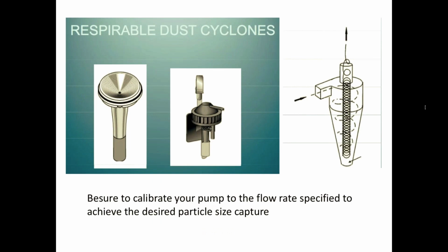Before we move on, another question. So you're saying that first I calibrate it, put it aside, put the new one in, and then take it out, put another one in, and calibrate. Correct. So let's say the first average was 1, and the second time I calibrate it again, I come up with, let's say, 1.5. Well, it's going to be lower, it's not going to be higher. So you come up with 1.75. So what do I do? You take the average of those two. That's the average flow rate during the entire period that it was exposed.